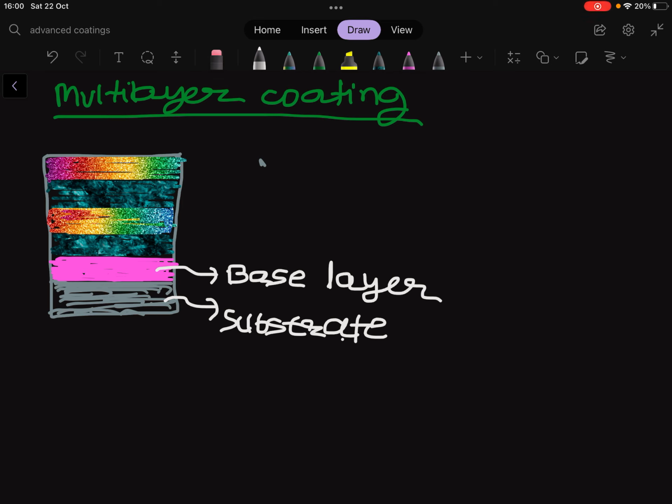We have a substrate. Now typically you apply a base layer made of metals, in order to ensure good adherence to the substrate and sufficient ductility to tolerate the different strain behavior of the ceramic material and ductile substrate, and then we may apply a sequence of layers in our coating. Actually, overall thickness is comparable to a standard single layer coating, and we are still in the range of some micrometers. So how can we produce this complex coating?